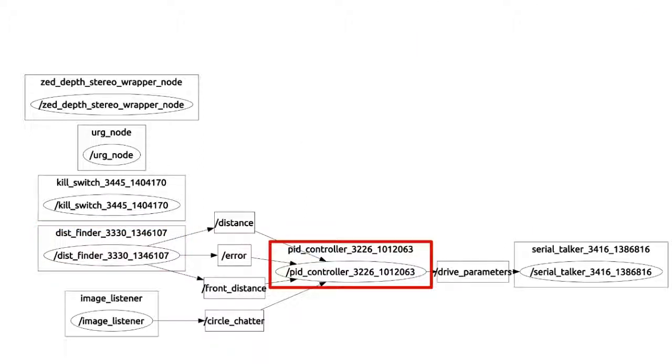The controller listens to four different topics. Every time a topic is updated, a callback function alters the state of variables defined within the node. The controller then computes the steering angle and the velocity of the vehicle. The controller can be in one of three states.